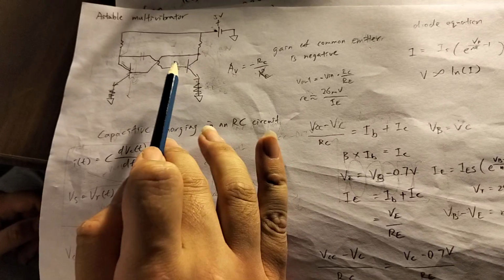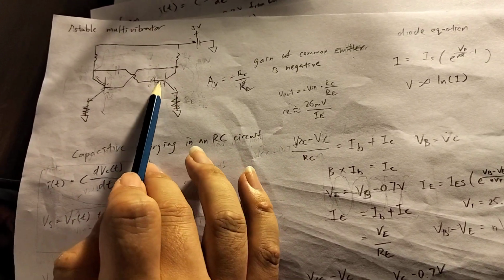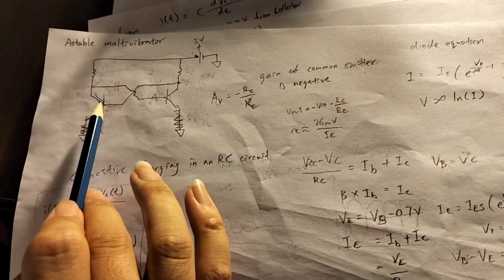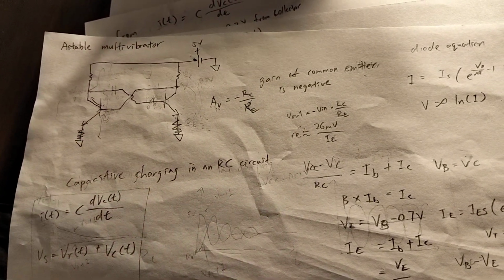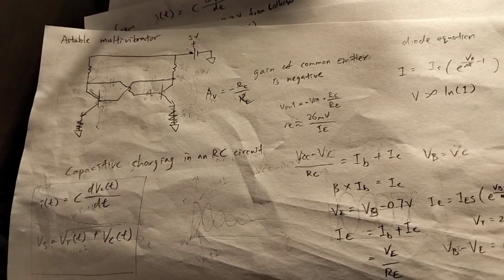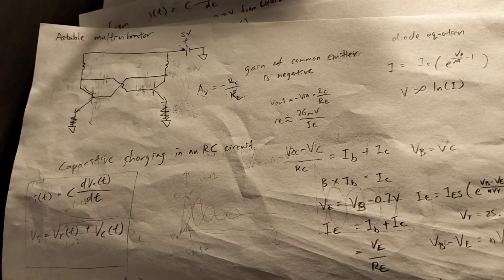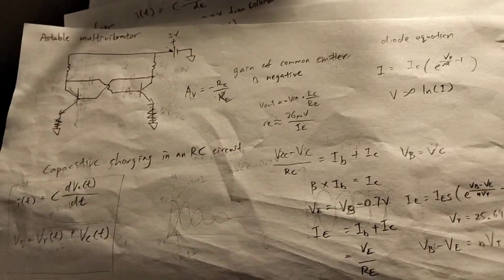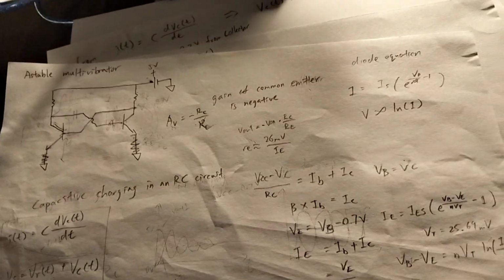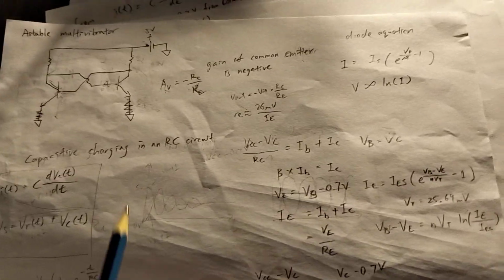And the reason why it does that is because one of the transistors becomes very close to saturation, and the other becomes very close to cutoff. Basically, one is going to be above the equilibrium collector voltage, and one's going to be below that. And essentially, a common emitter configuration will always go through a gain of 1 as it comes close to saturation and as it comes close to cutoff.